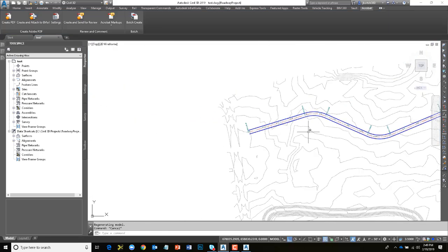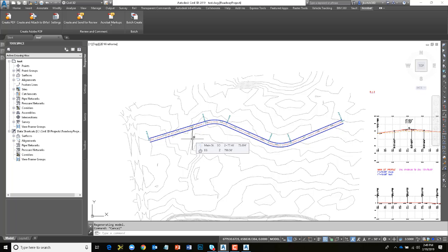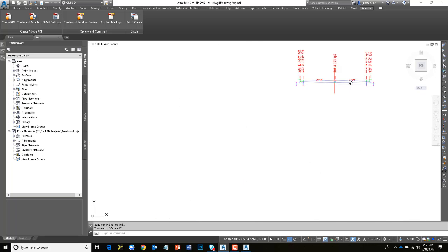So now I'm taking and just using that number generator as a means of driving the dimensions of the parts that are already available out of the box in Civil 3D. The nice thing is I can have as many of those number generators as I want. I could keep bringing those in, dropping them. You always want to drop them to the inside as close to the beginning of the assembly as possible, because that way the objects that are to the right or to the left, depending on how they're inserted, you can have them look at the one that's prior to it to calculate that, or to grab the number.